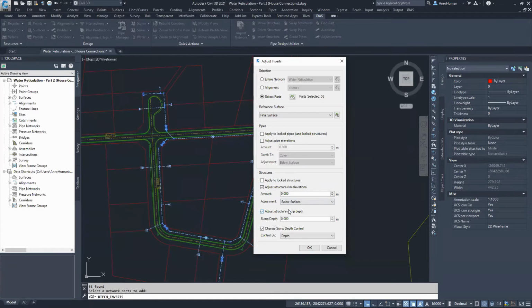Now, these need to be adjusted to sit in line with the pipes, right? The rest of them are all stretched towards ground. Now, my pipes are at 0.8 below ground, so I can change this to any value more than that. So let's say 2 meters below surface. The reason why I select a larger value is because these objects will be stretched down, but they cannot be stretched further down than the pipes. So they will basically be snapped to our pipes. So that's going to be 2 meters below surface. You can even choose 5 or 10 or whatever. It won't go as deep.